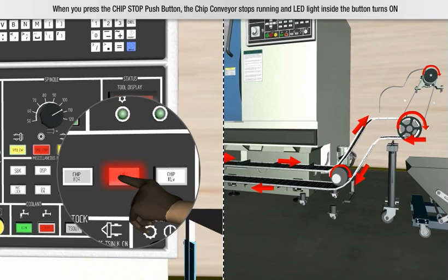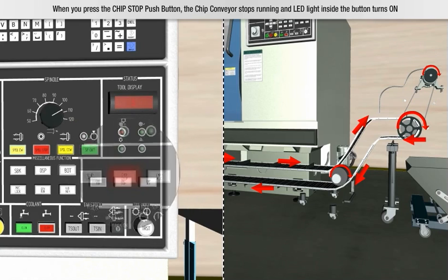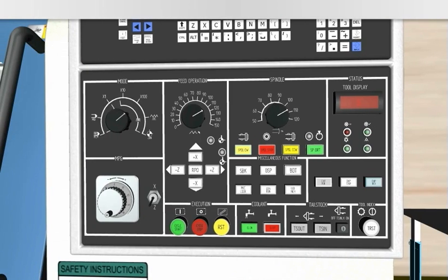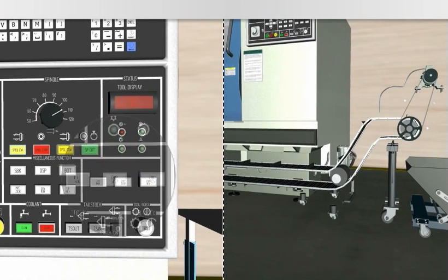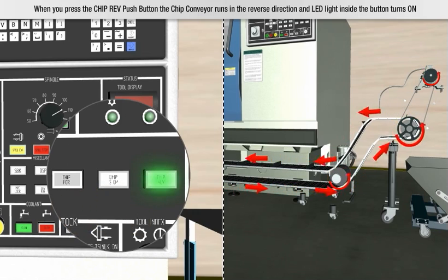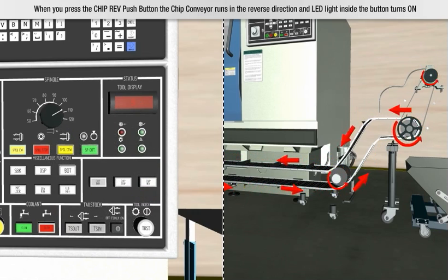When you press the chip stop push button, the chip conveyor stops running, and LED light inside the button turns on. Chip conveyor reverse. When you press the chip reverse push button, the chip conveyor runs in the reverse direction, and LED light inside the button turns on.